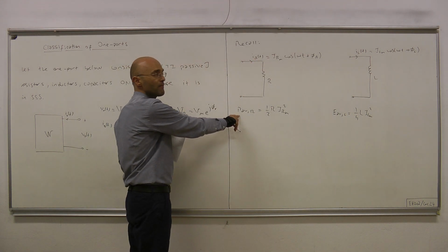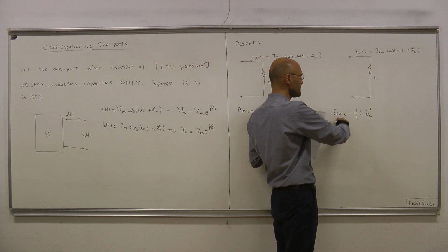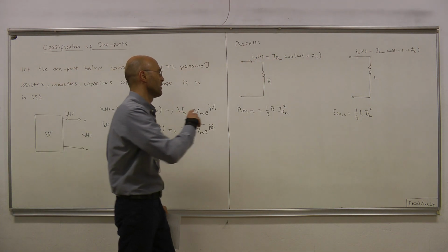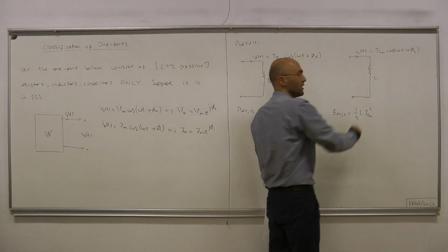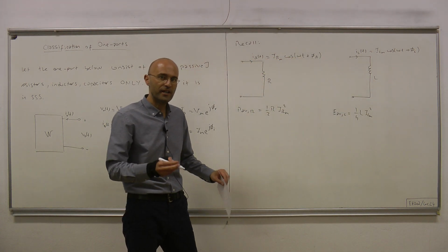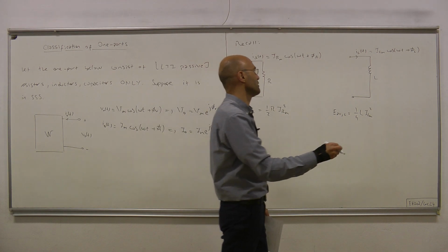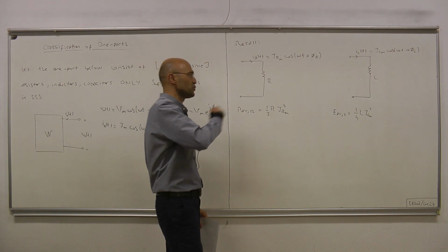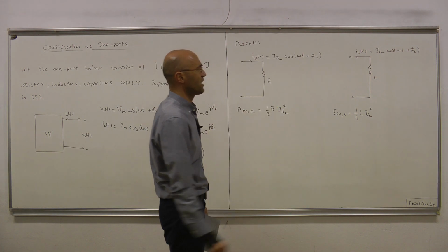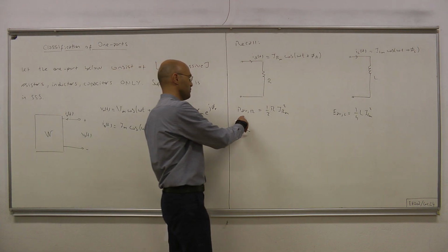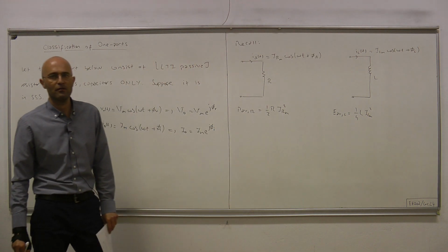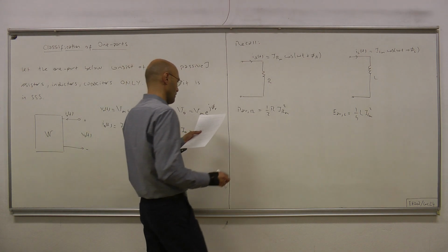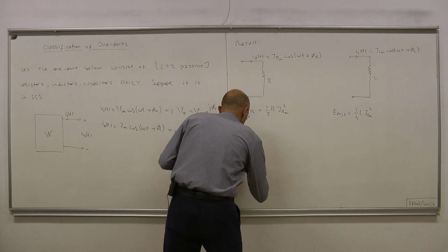As for the average power, both for inductor and capacitor, it was 0. We interpreted that as follows: at certain times the inductor takes energy from the circuit, and at other times it gives back the energy stored earlier, and the giving and taking balance out perfectly, which produces 0 average power. The same holds for the capacitor.